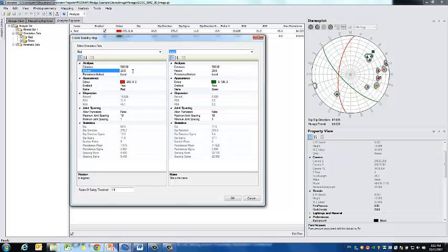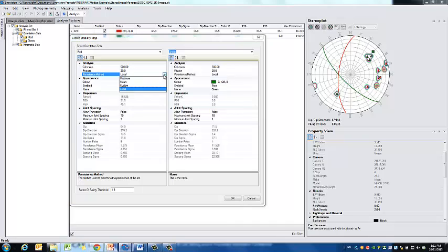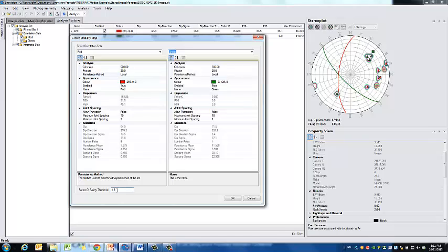And those wedges, if detected, are given a classification. Other values in here you can edit is the persistence method. You can use local or use the maximum persistence of that set, or use the mean persistence. That is the persistence it applies to the two planes, which it will compare to see if they intersect to form a wedge. The last thing we input here is a factor of safety threshold.